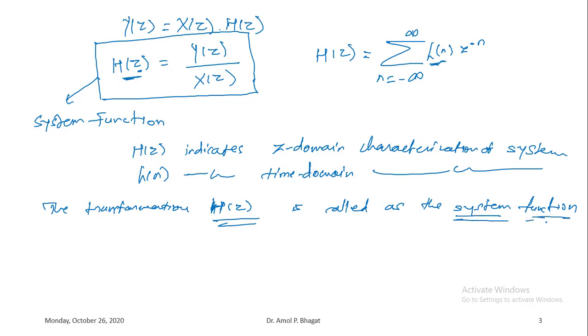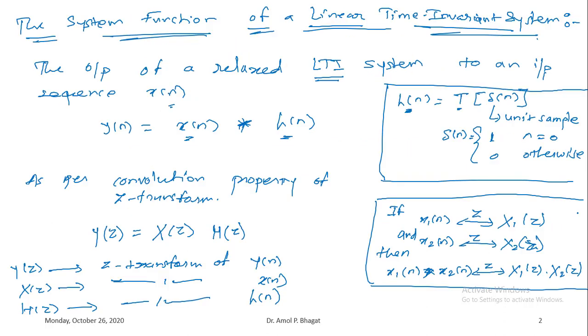This is when we are identifying the response of a system by using convolution summation, right? In case of an FIR system, we can use convolution summation. But if the system is an IIR system, then we cannot use convolution summation to identify the response of the system. So to this convolution summation, we applied the convolution property. As per the convolution property, this convolution will be multiplication in Z domain. So it will be X of z multiplied by H of z.